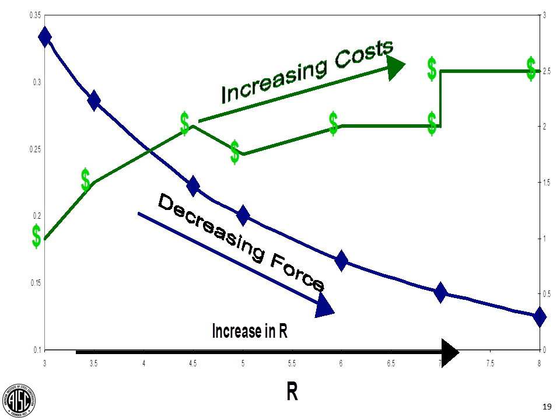And so as we would expect, as we increase our R factor, we're decreasing our base shear, we're decreasing the force that's going to be seen by that structure, and so overall the force has been reduced, and some people might think that would result in a more economical structure. But in fact, all the detailing requirements that we have to ensure that these things behave ductilely with all this inelastic behavior going on can increase the cost of the structure.